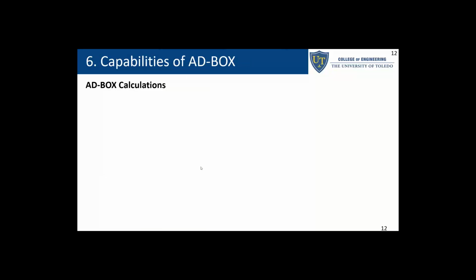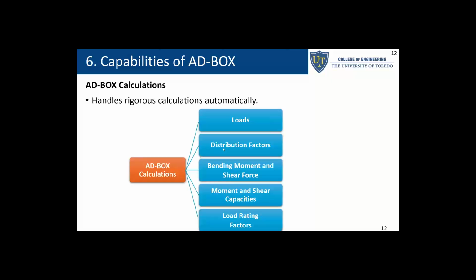So let's look into the capabilities of ADBox. ADBox can handle rigorous calculations automatically. The calculations include dead loads and live load distribution factors, calculation of bending moment and shear forces, calculation of nominal moment and shear capacities, and finally the calculation of final load rating factor values.